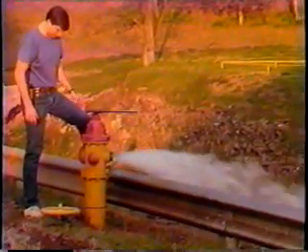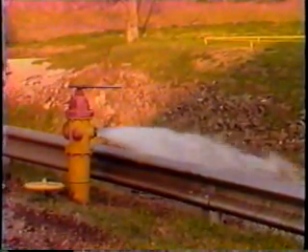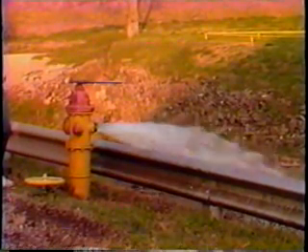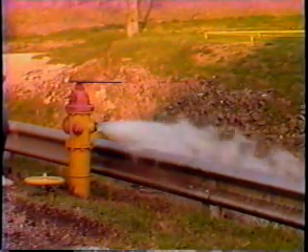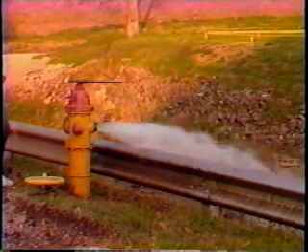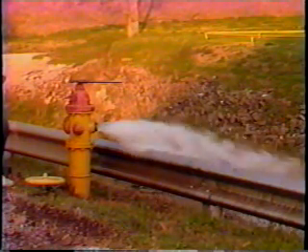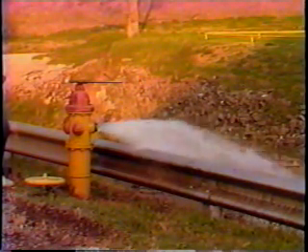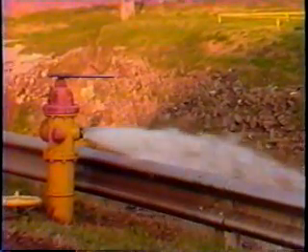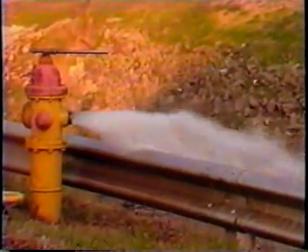During a hydrant flow test, you should expect to get several hundred to over 1,000 gallons per minute out of a float hydrant. If you're only getting 100 or 200 gallons per minute out, as you see here, it's usually an indication that something is wrong during the test.